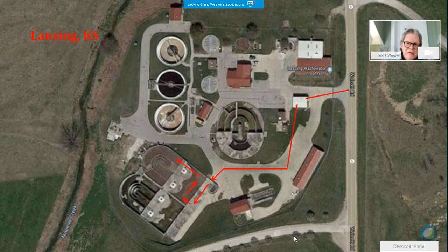So it goes through the anaerobic zone, then goes into an anoxic zone, and then there you can see that channel that connects the anoxic zone to the aerobic zone. The wastewater flows around that. I'll back it up. Of course, in this anoxic zone is where you get the nitrate conversion to nitrogen gas, and the ammonia removal is in the main body of the ditch, and it sends the nitrates back into this anoxic zone. Final effluent goes out to the receiving water.